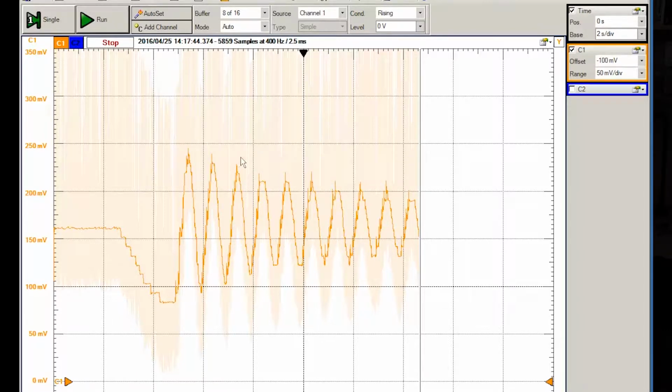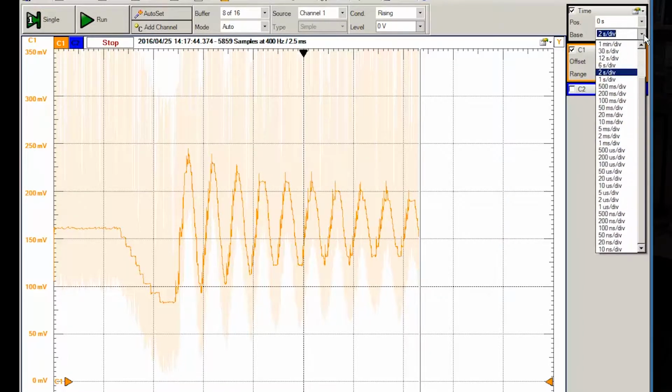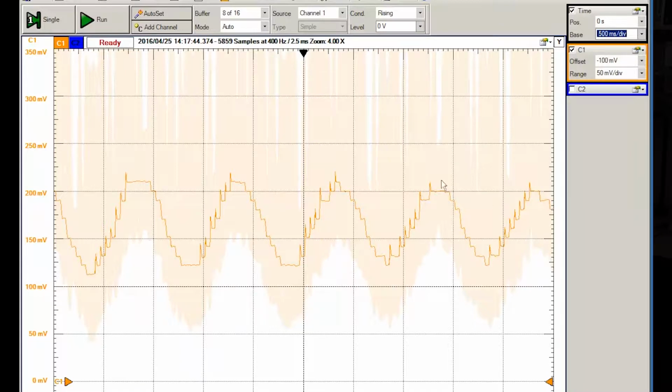Another problem is that there's a lot of noise in the signal, which is causing this jagged stuff in the signal itself. This noise is just random fluctuations in the output voltage due to non-repeatable outside influences. I can see it a little better by zooming in on the time scale. Notice that the noise changes much more rapidly than the platform moves, so the noise is said to have a much higher frequency than the actual data. To fix these problems, I'll create a circuit that will increase the voltage levels indicating the platform position while decreasing the noise levels.